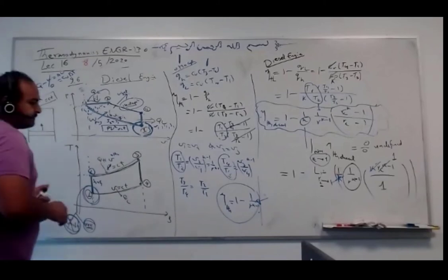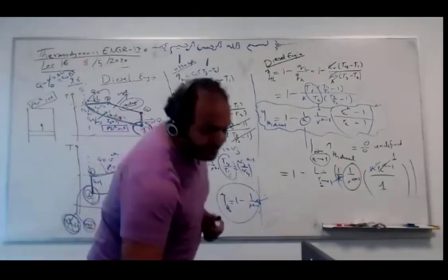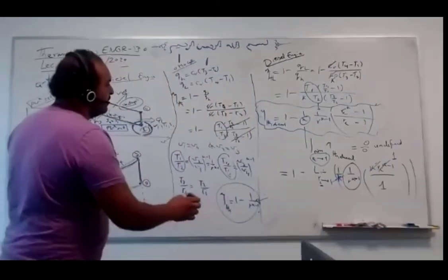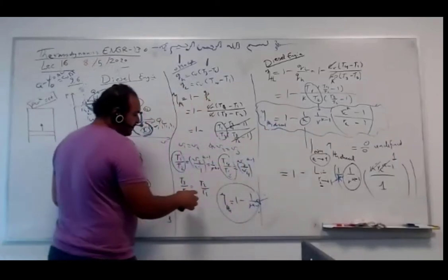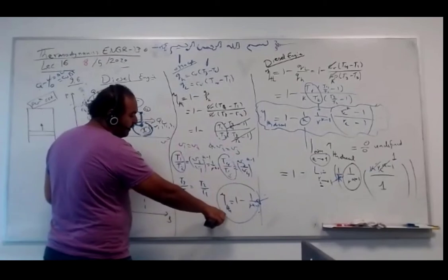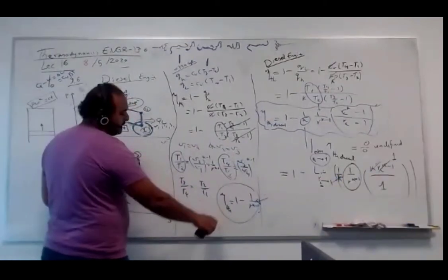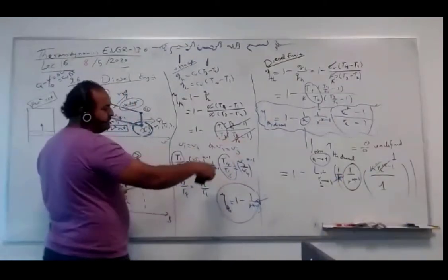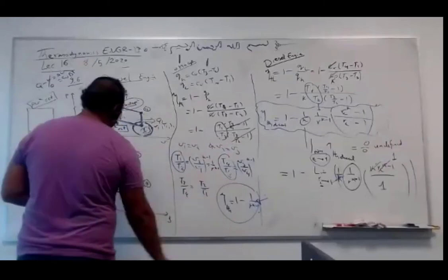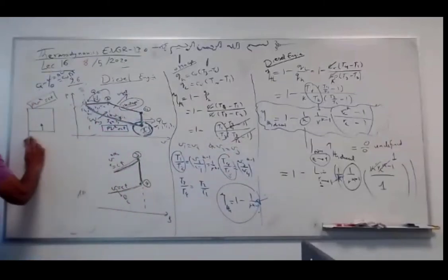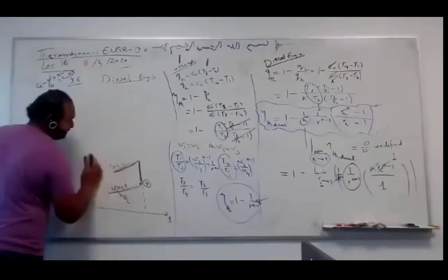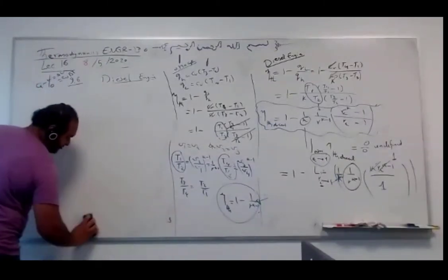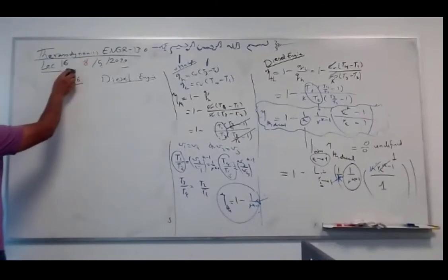So let's take an example. For diesel, if you have R_c and R, and of course you have K, you can get the diesel thermal efficiency. And if you have R and K only in the Otto, you can get the thermal efficiency, because there is no R_c there. Let's take an example in Otto and an example in diesel. Okay, guys? Get excited?